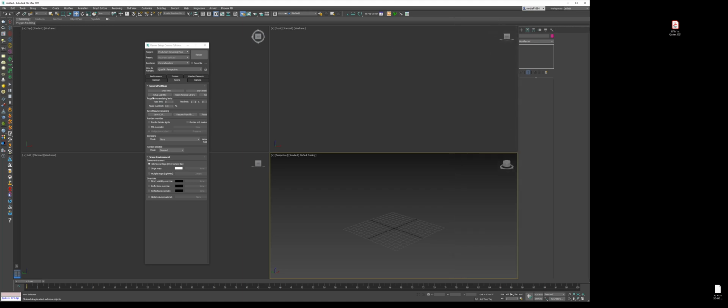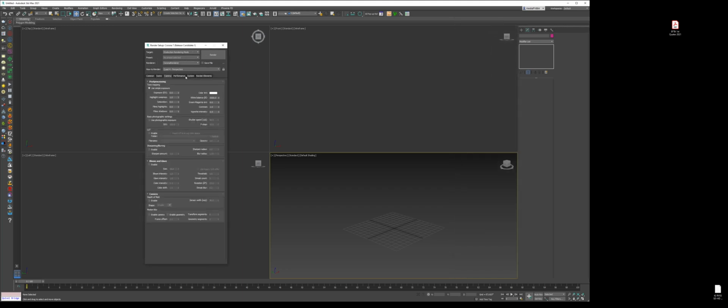What we'll do is, here under the camera tab, under the renderer, we're going to change this right away to use photographic exposure, ISO 100. We're going to do F8 and shutter speed is 200. And typically this is my foundation, this is what I usually use, and actually f-stop will do 5.6. That's kind of what I usually like to shoot at in real life when I shoot backplates, so that's kind of my go-to guide. So then the next thing we'll do is we'll check the bloom and glare.